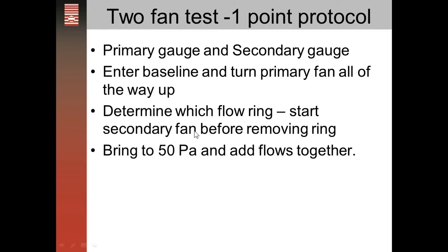Before you take the rings off on the second fan, you'll want to start that fan running. Otherwise, when you take the rings off, the blades will turn backwards on the fan. So it's important before taking the rings off on the second fan, get the fan blades moving and get them moving fairly fast before you take the rings off. Otherwise, the blades will be turning the wrong way on that second fan.